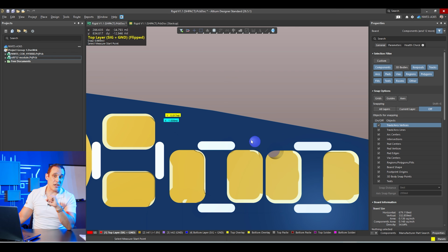Now, normally it's good advice given by manufacturers to pull back any copper elements by at least 10 mil. And that would just be for like copper pours. And if we're talking about actual components, they might tell you to pull it back more than 10 mil. So this is another thing where a manufacturer is going to send this back to you and ask you, the designer, to correct it. Now, maybe they don't send it back to you. Maybe they just give you a warning and they tell you, hey, when the board gets cut out of its panel, the route might cut into that SMD pad, and that's just a risk that you may have to accept. But generally, it is in your best interest to just move those components back a little bit and make a little bit of room to the board edge.